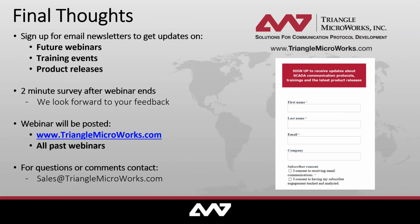There may be constraints from the vendor that will need to be documented, that when you change one logical device mode, all the others change as well, because they cannot have part of the device in test and another part not. The good way to model that would be to use now hierarchical logical devices and have one top level logical device, and only allow the change of the mode on that level, if the device has limitation with that regard.